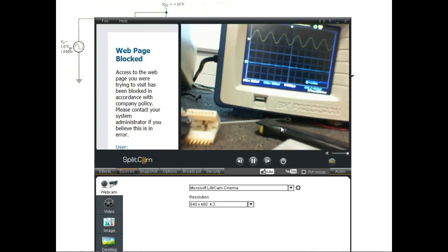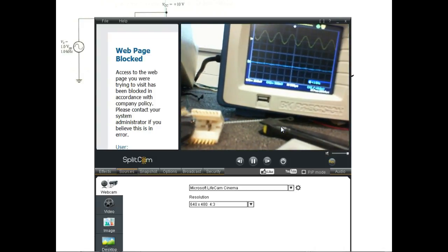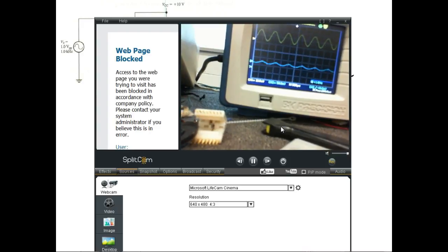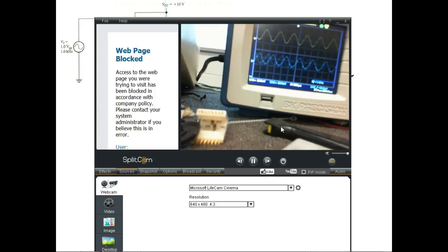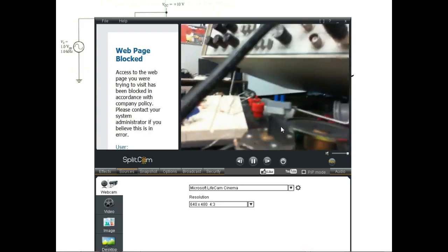My output went to 0 because the transistor is flat saturated. It's probably not 0. It's just that we don't have it turned down long enough. What you'll find out, guys, is AC gets through anything. So it's still there, but it's almost nothing, right? That's 10 millivolts, 10 millivolts. Let's come in, let's measure our bias voltage.